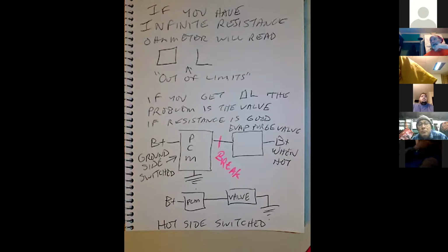Yeah. Okay, I'll believe that. Like, for example, your PCM, it'll tell you your PCM is located under the passenger seat. That's a component locator, which is different. At that point, you take your seat out and start looking around under all the carpet to find the ground.